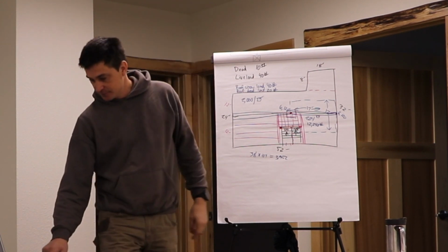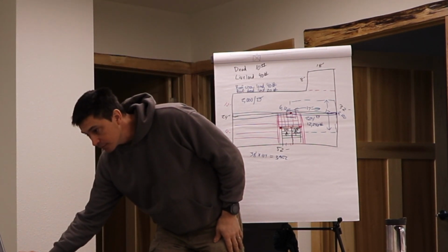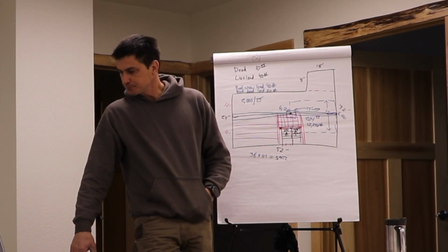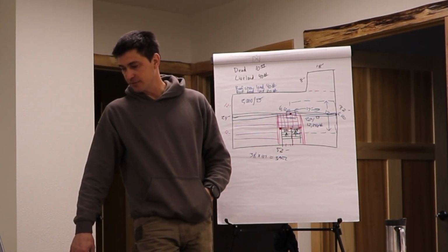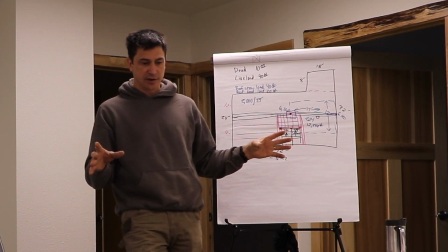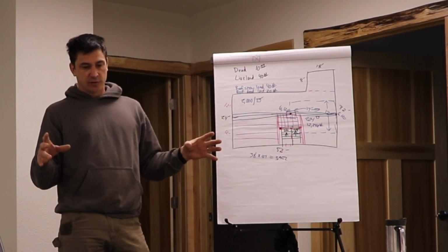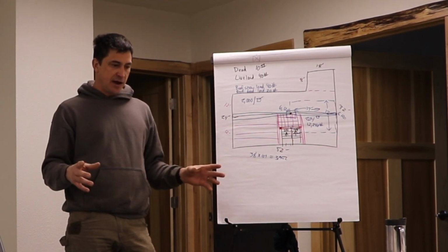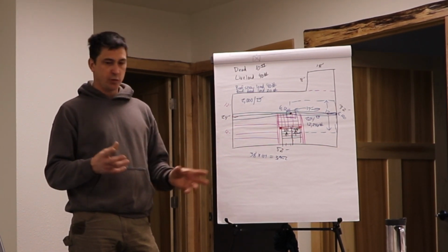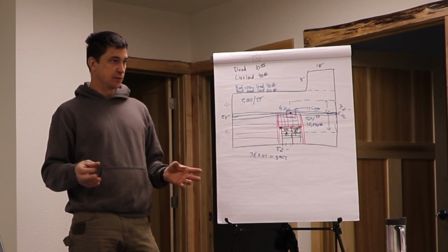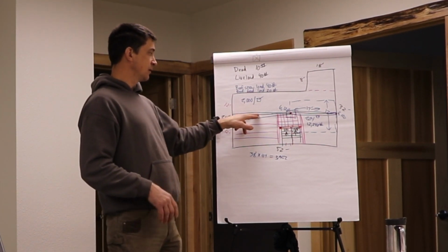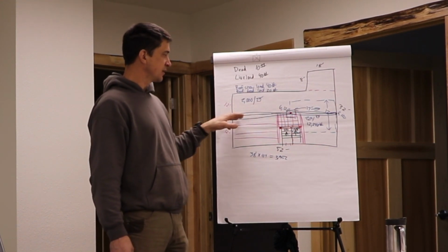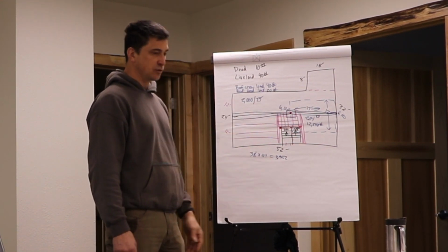Let's see, go back to slideshow here. Okay, so that's part of it. You have to look at it and be like, do I have what it takes to build this the way it's drawn? And if not, can we tweak the way the drawing is set up? You know, maybe if they're willing to put another post in here, this could get re-engineered and probably cut the weight in half.